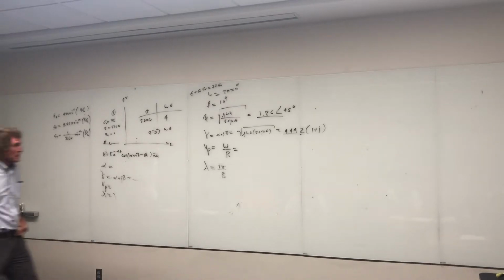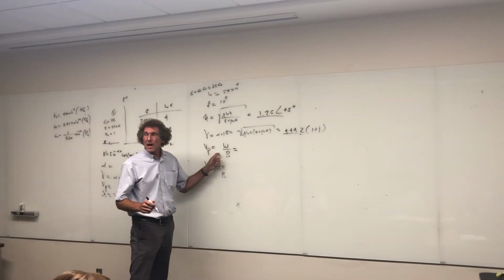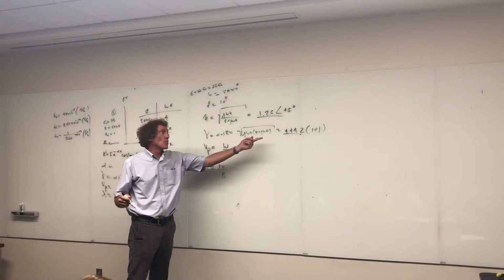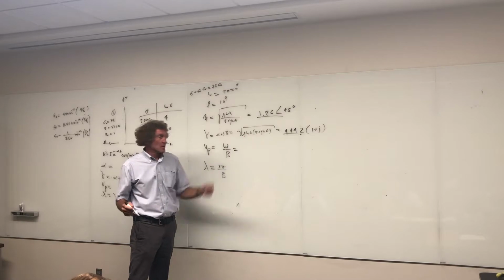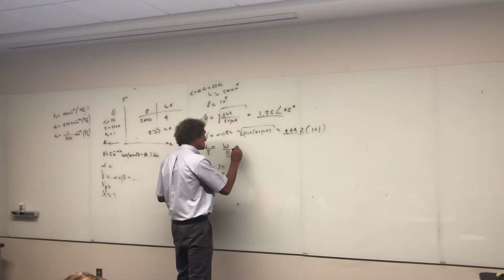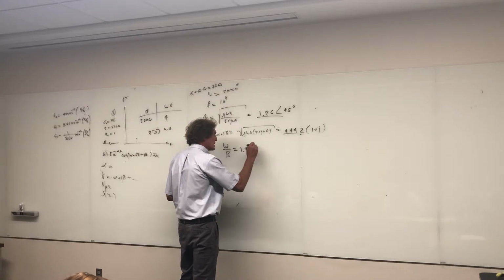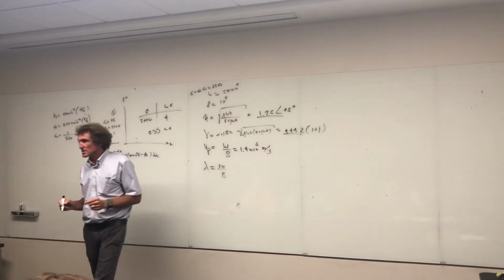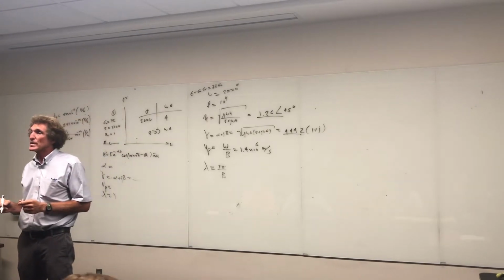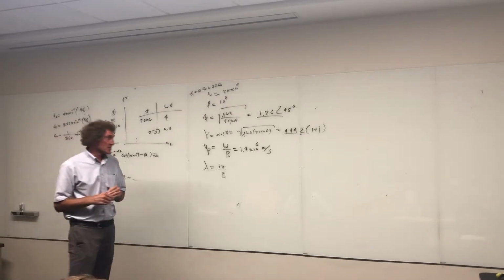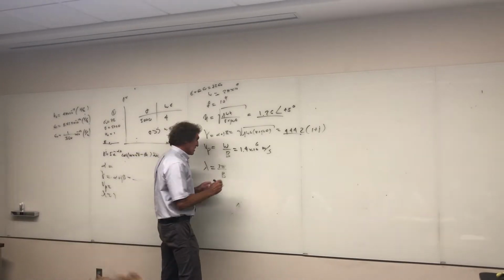Great, great. What about the phase velocity? What is it? You got omega, you got beta is 4,442, right? Do the division. Class? 1.4 times 10 to the 6th meters per second. You realize that's much, much less than the speed of light. The speed of light is 3 times 10 to the 8, correct? So it's much, much less than the speed of light in a vacuum.